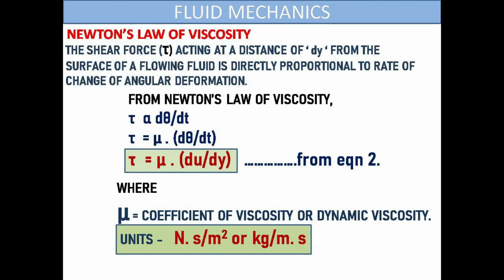Newton's law of viscosity. The shear stress acting at a distance of dy from the surface of a flowing fluid is directly proportional to rate of change of angular deformation. This is an important fluid law. That is, shear stress is directly proportional to rate of change of angular deformation. Tau is directly proportional to d theta by dt.